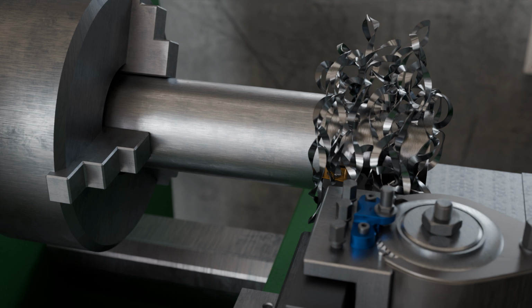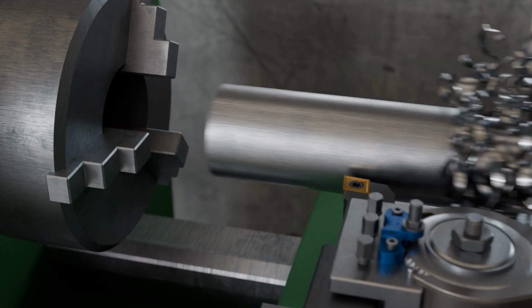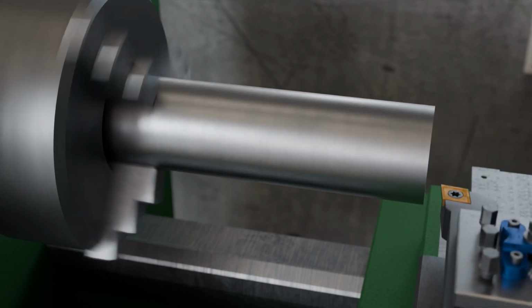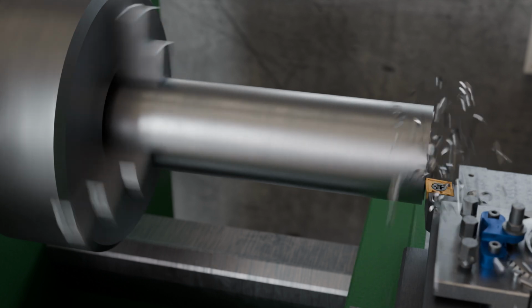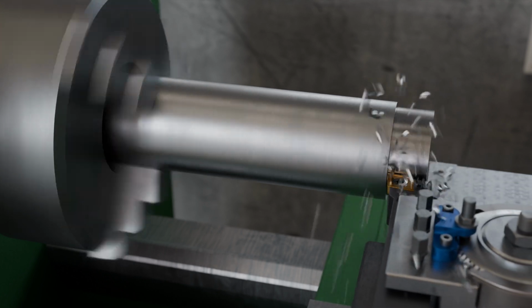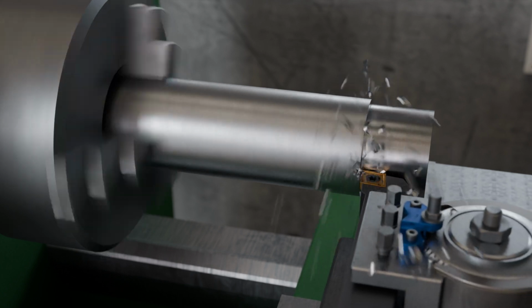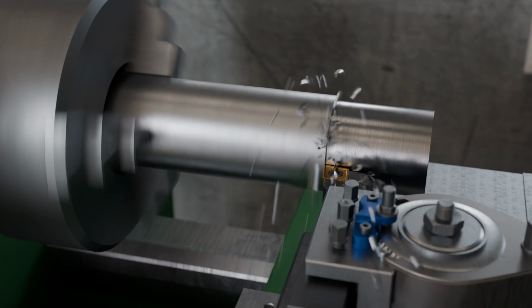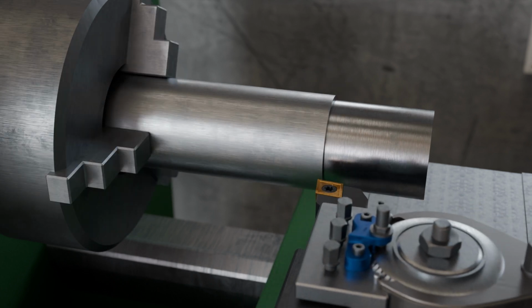The tougher and softer a steel is, especially those with low carbon content, the higher the risk of producing long stringy chips. Therefore, steels were developed that, despite a low carbon content, tend to produce short-breaking chips. Sulfur has proven particularly effective for this purpose, especially in combination with manganese or lead. These elements form low-melting iron manganese sulfides in the microstructure, which promote chip breaking and result in short, fragmented chips.